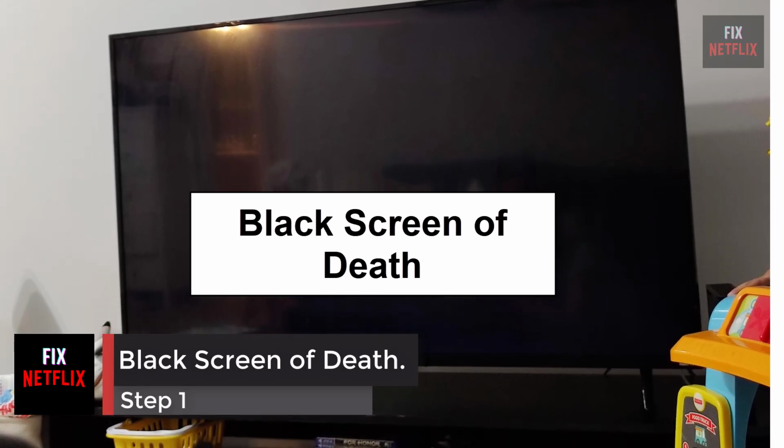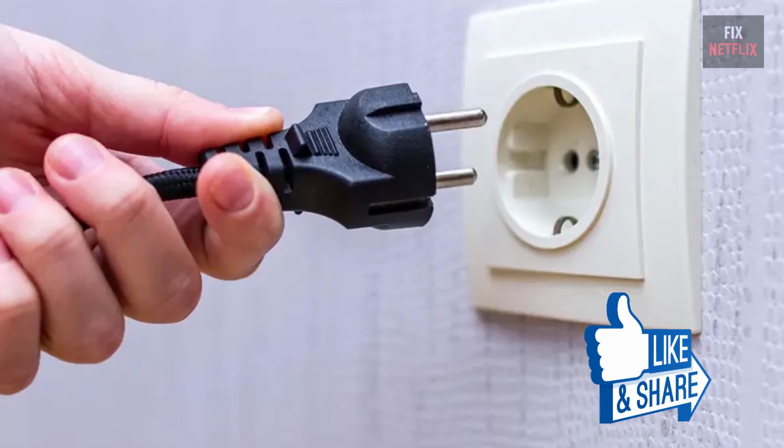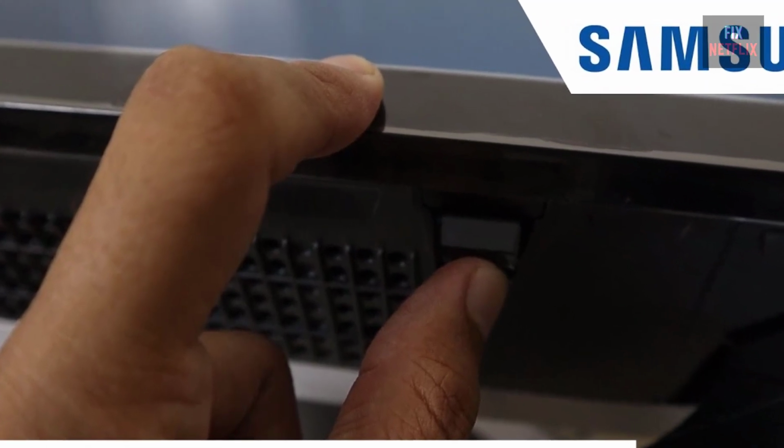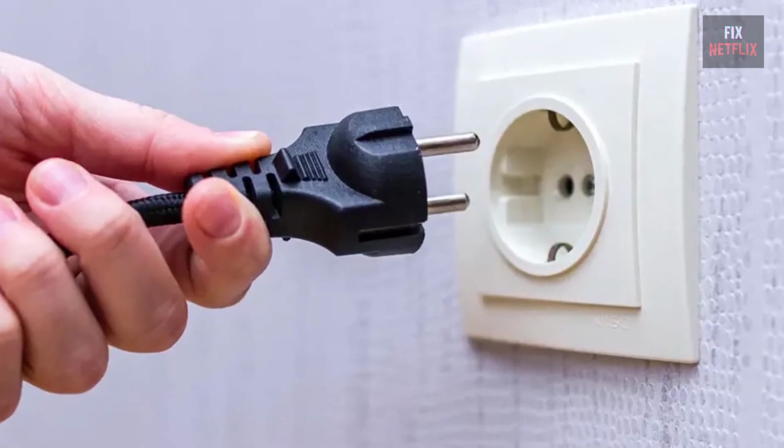Let's start off with the most frustrating and serious situation. The black screen of death is a term used to describe a situation where a TV displays a black screen and is unresponsive to user input. To solve the problem, please follow the steps. Firstly, unplug the TV from the wall outlet. Then press and hold the power button on your TV. Remember to hold the button for at least a minute. Then plug the TV back in and turn the TV back on.